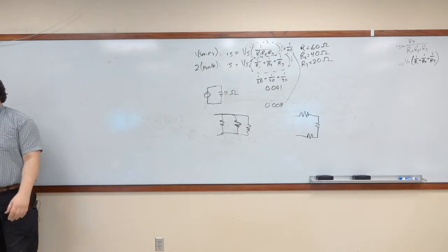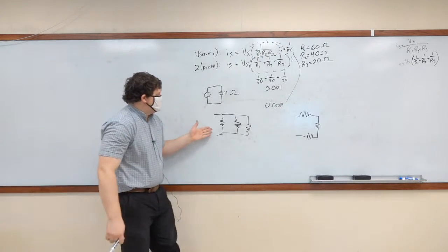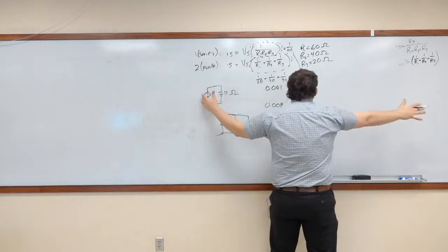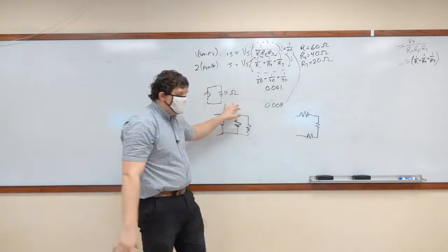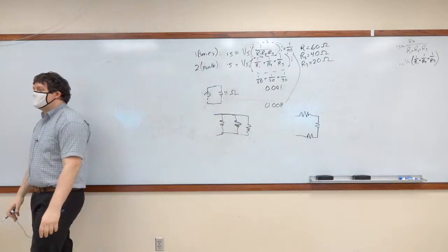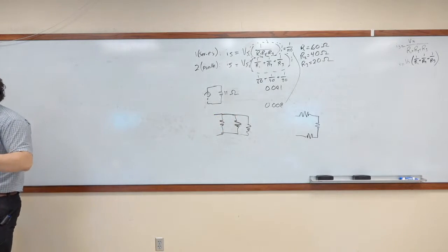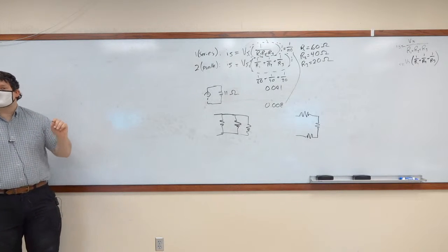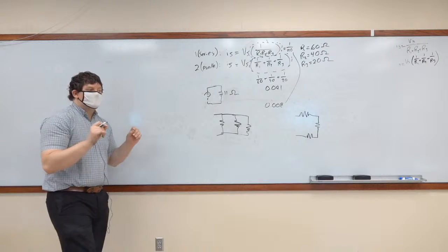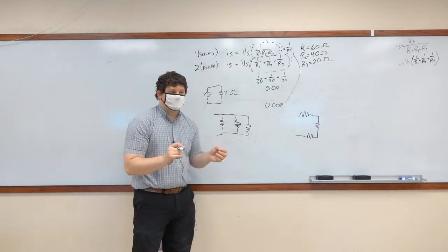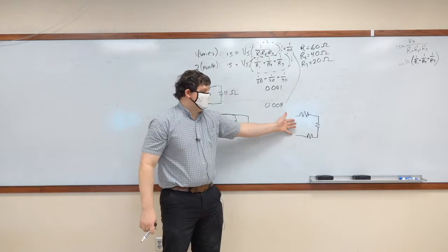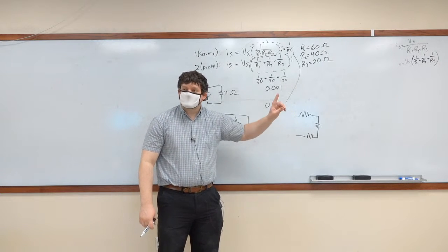Nothing else matters. It doesn't matter if you have components in parallel series. It doesn't matter if your system is so large it spans this board. As long as the equivalent resistance comes back to 11, they're identical as far as the battery is concerned. Okay? And that allows us to simplify the circuit significantly. Equivalent resistances let us take this one and calculate it as if it was one resistor.